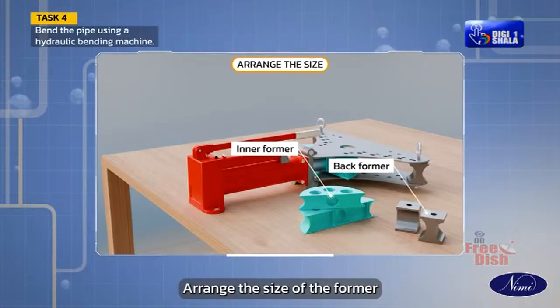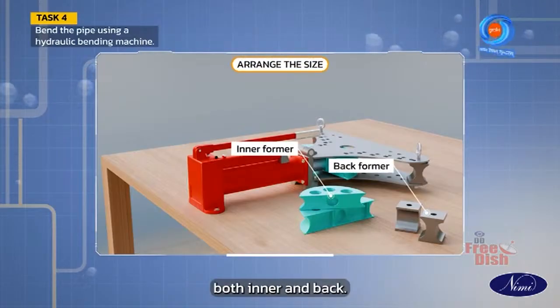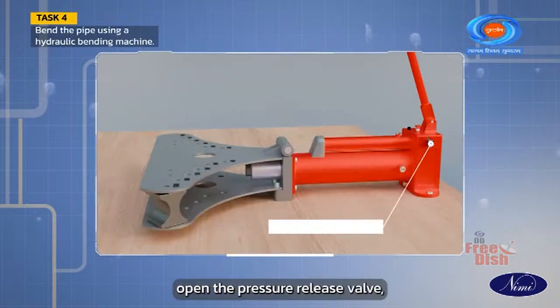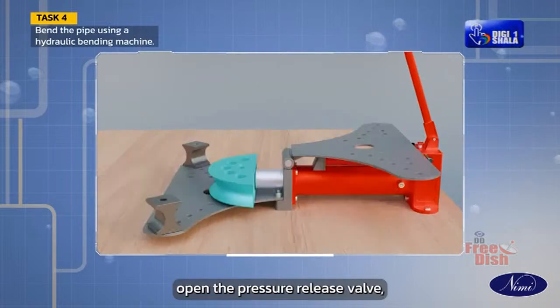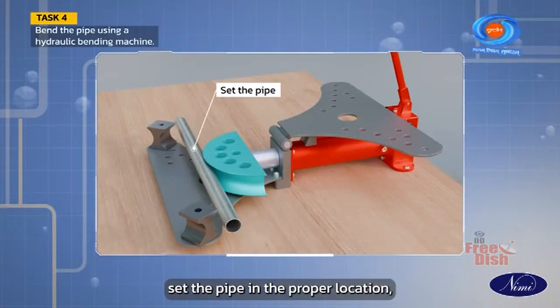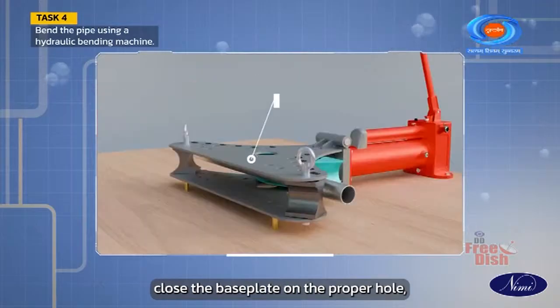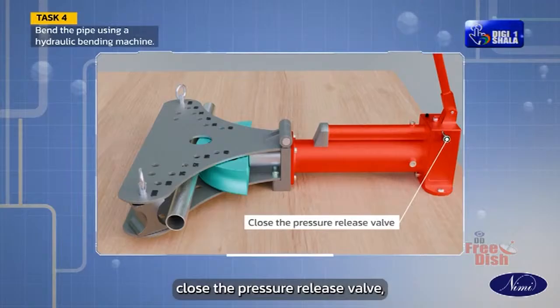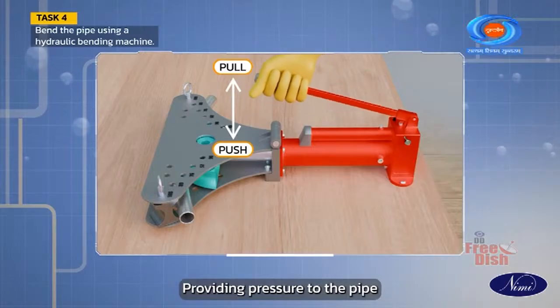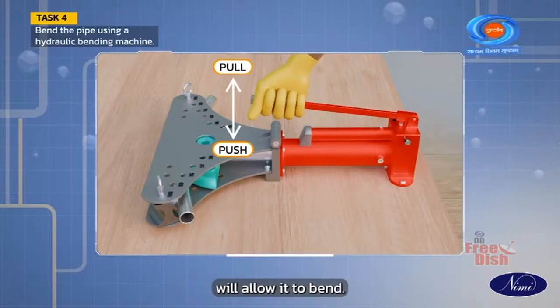Arrange the size of the former, both inner and back. Set the former. Open the pressure release valve. Insert the inner former. Set the pipe in the proper location. Close the base plate on the proper hole. Close the pressure release valve. Pull and push the operating lever. Providing pressure to the pipe will allow it to bend.